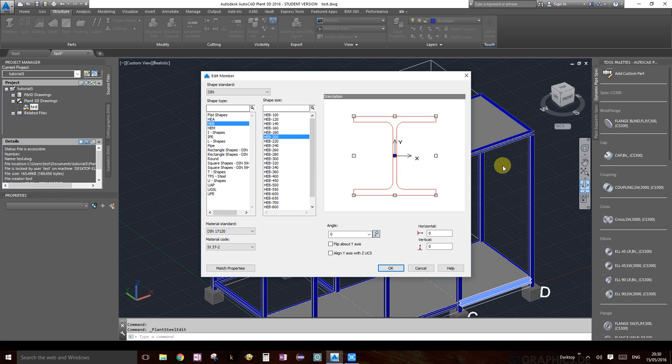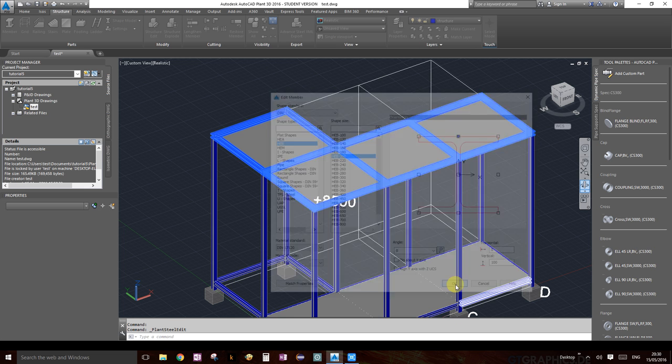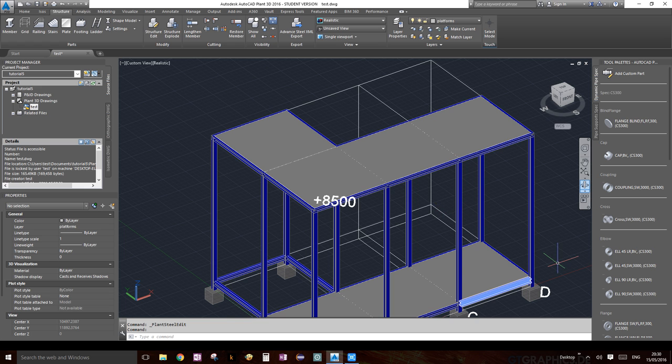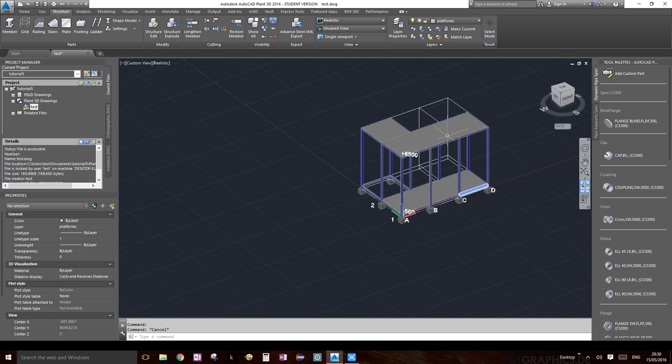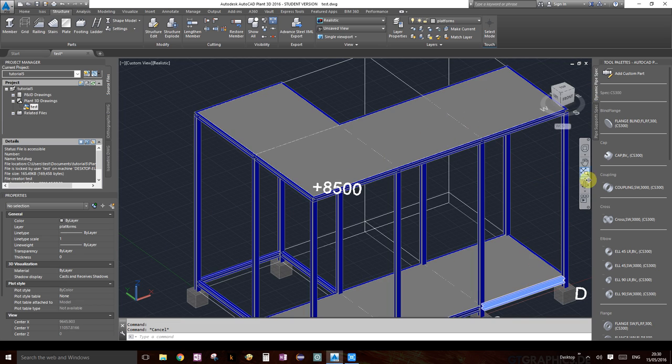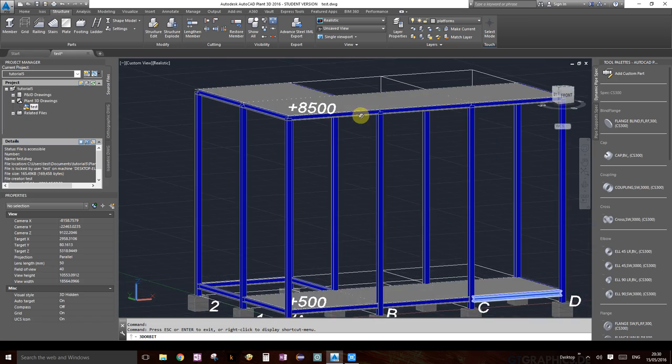So what I've done there is selected all the upper horizontal members and clicked on structure edit, and I'm going to say orientation is top justified, everything else is the same, and bam, it's done. Now our grading has moved to the proper spot. Now you can't see them through it, because obviously in real life you won't be able to see through that.